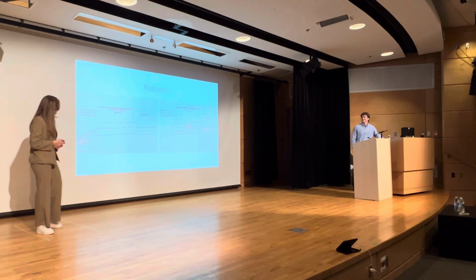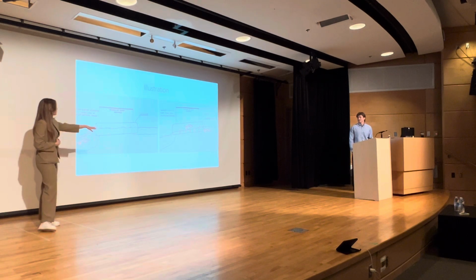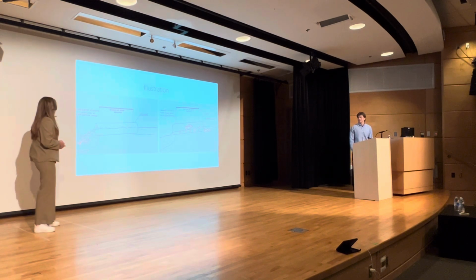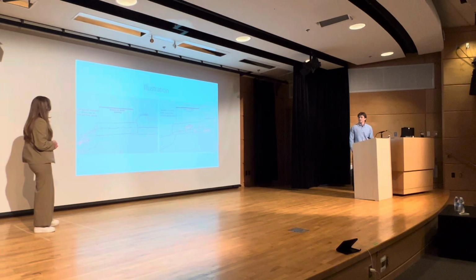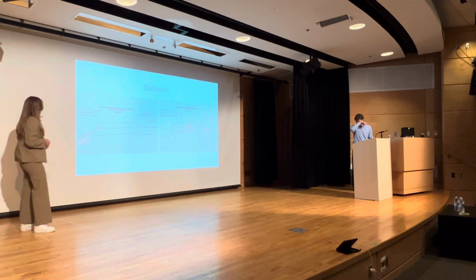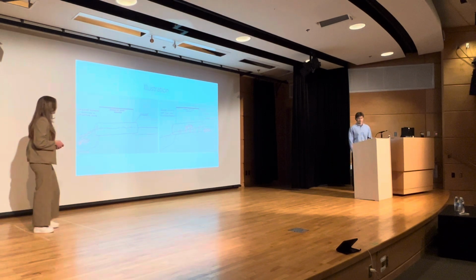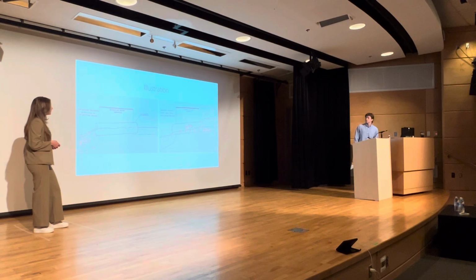This is a little illustration of what happens with normal culverts and culverts with fish baffles. On this culvert, we have a high velocity here, which results in the fish getting stuck over here. And then on this culvert, we've included baffles, and they create these little resting areas with slower velocities, and the fish can jump through all of them. And we have a happy fish and a happy ecosystem.